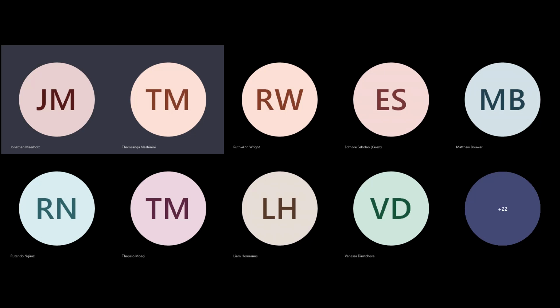Okay. That means I made a mistake somewhere. Yeah, you've made a little error, maybe with your capacitance. Did you see it's 1,000 nanofarads? Nano is 10 to the negative 9. Yes, that's right. Then to get the inductance per length, you have your capacitance per length and your characteristic impedance, and you can solve for it using the characteristic impedance.